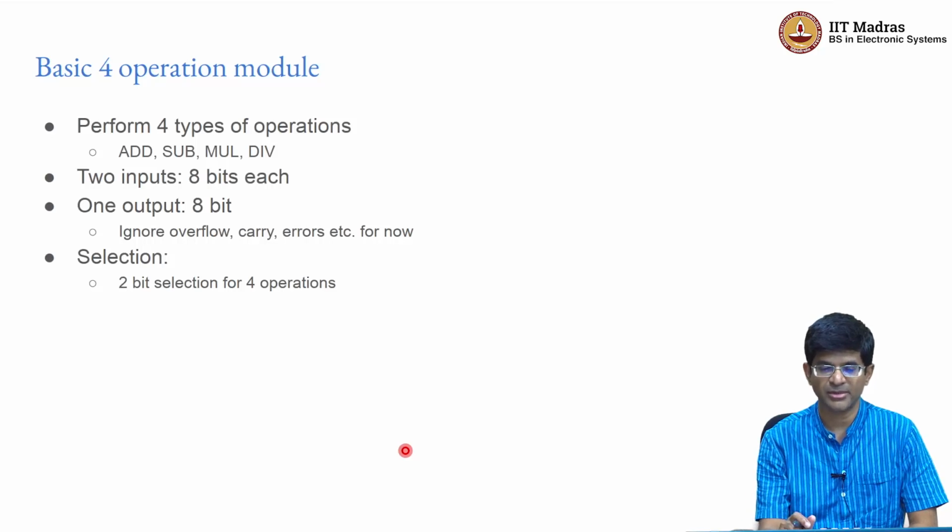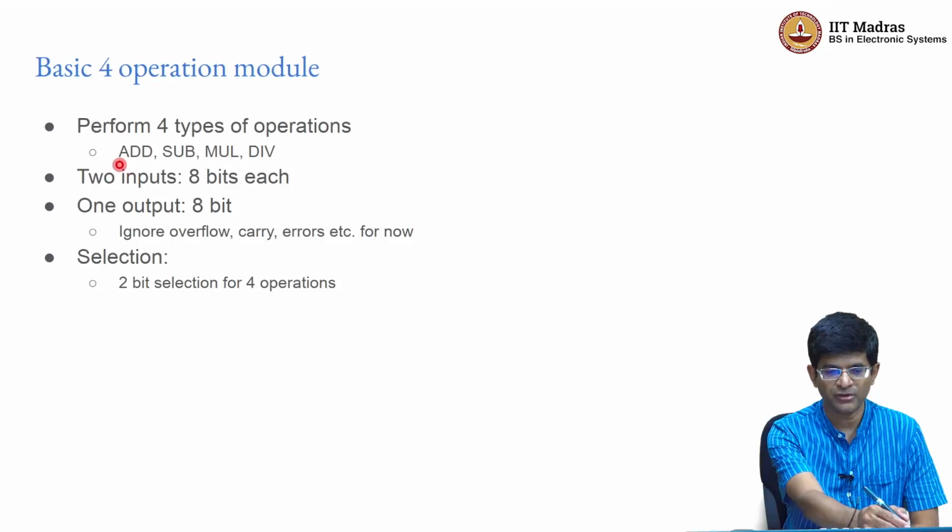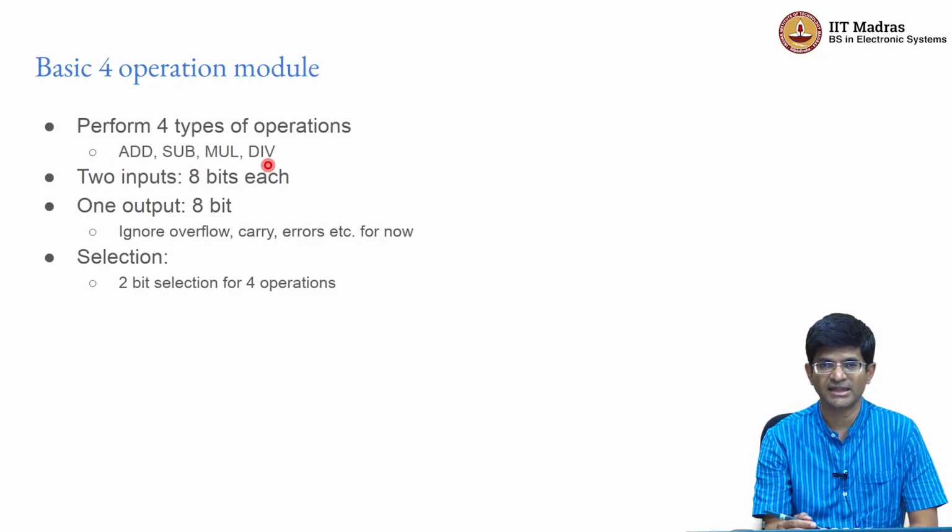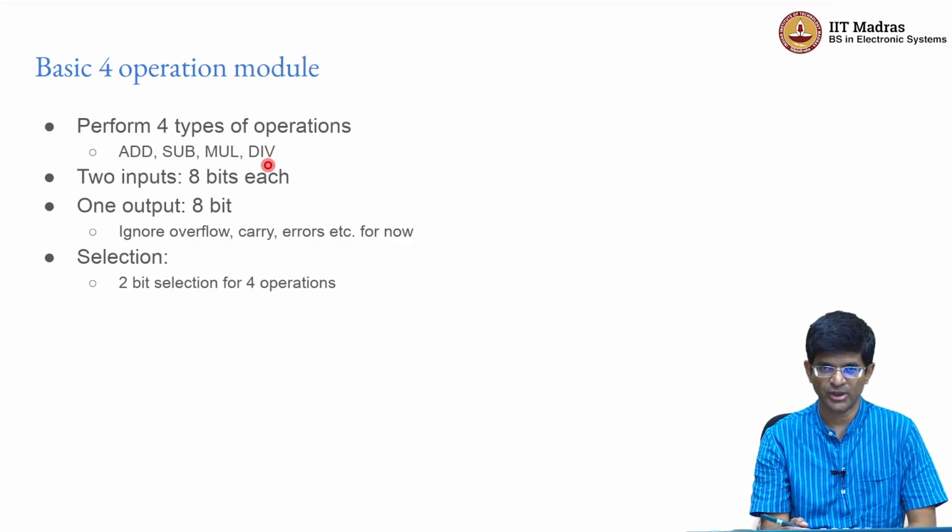which is the discriminant computation. And we are going to assume that we have an arithmetic unit that can perform 4 types of operations. It can add, it can subtract, it can multiply, and we will also assume that it can divide. Now technically, as far as the discriminant computation is concerned, neither the add nor the divide are required, but that's okay. We want to have a solution that could be used for other things in future as well.